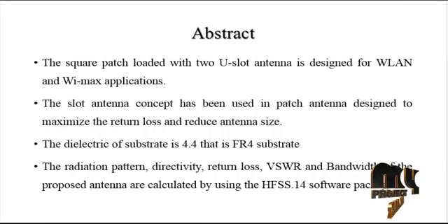The first method, the resonant frequency method, utilizes the extension of the four distinct resonant frequencies, while the second one, the dimensional invariant, that is DI, relies on the property of DI to design the U-slot microstrip patch. In both of these methods, the optimization of the probe location is necessary for further enhancement of the 10 dB return loss bandwidth.